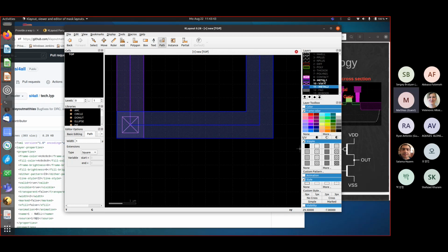And these layer properties are pretty mighty in terms of configuration. For example, you can create tabs. You can duplicate the content of this layer list above, so you can create different views for different purposes, like people seeing only certain layers, or having other colors, or setups for a white background and a second one for a black background, and things like that. You can also group layers and so on. So this is quite a powerful concept, but that's a topic on its own.